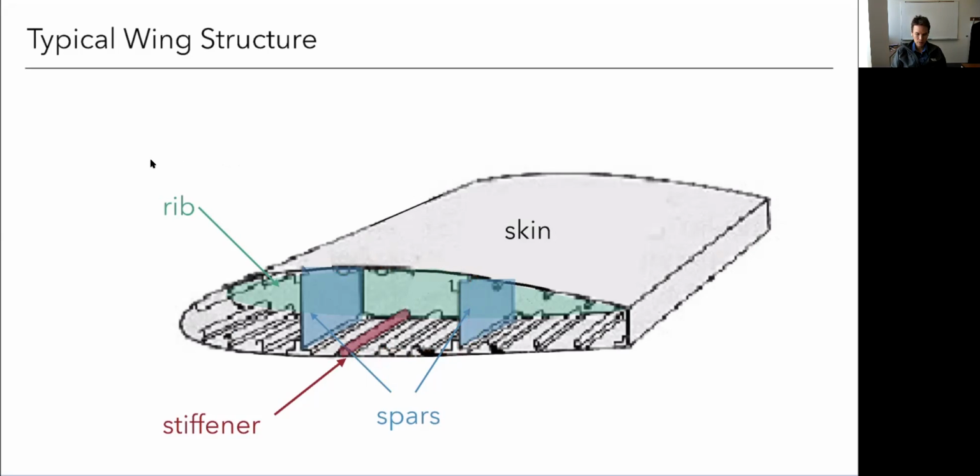These spars are also going to carry some of that vertical load, but what else will the spars do? Imagine I don't have the spars, I just have this vertical section. If you remember from structures, that's going to really increase my torsional rigidity, so that's going to help me with torsion. So those are going to help stiffen that up. Sometimes in other applications, these will be called shear webs, but similar concept here. Okay, so this is what a typical wing structure might look like.